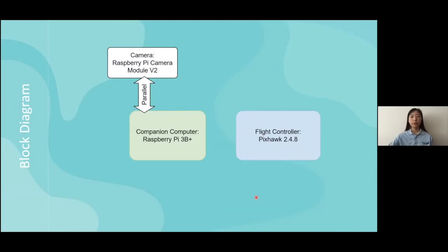There used to be a servo attached to the camera, which allows us to get up to 180 degrees of view, but we had trouble with vision transformation. With a moving servo, we need to configure different sets of parameters at different angles. So we decided to use only a fixed down-facing camera for detection, and that's enough for searching the tag when the drone is up in the air.